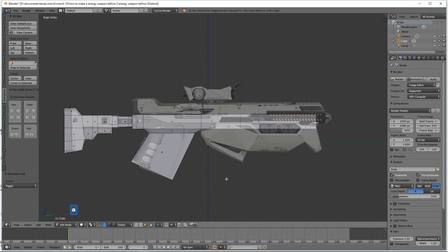I'm going to press A to deselect. Okay, there's multiple ways of doing that. What I'm going to do is hold Control, and while holding Control, press R. That put a loop cut in. I'm going to left click one time. Because I left clicked one time, I can move this loop cut. So I'm going to move this up to here. What I'm doing is putting this loop cut fairly close to this other loop cut here. I'm then going to press A to deselect.